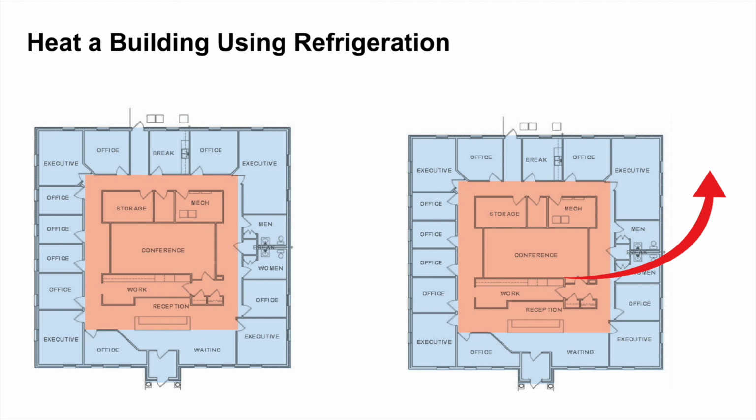Of this theoretical floor plate here, the perimeter zone, or the blue zone, in the wintertime, those spaces will need heat. They're right up against the perimeter glass, with the different sources of heat transfer that Matt introduced. There's conduction through that glass, it being very, very cold outside, and the occupants right on the inside of that glass need to feel warm. So those spaces will need heating.